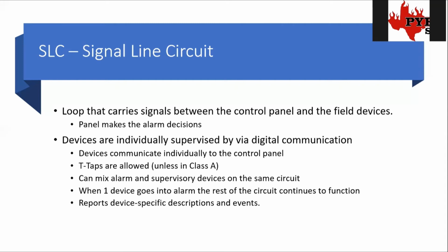So if you're trying to figure out how to meter it before you wire it up to your panel, say it's you and a helper there, send your helper to the far side of the building, you stand at your home run, and you can still set your meter to that resistance setting and check the meter, and with your helper on the phone or on a walkie-talkie or something, tell them, hey, short these wires together and open them back up, and you should be able to see them shorting and opening them up on your meter there. If you can't see that, that means that you have an open circuit somewhere between those 2 points.